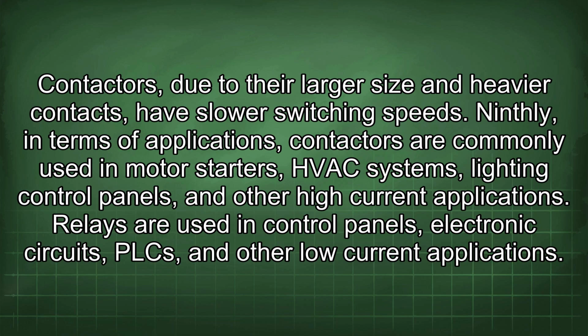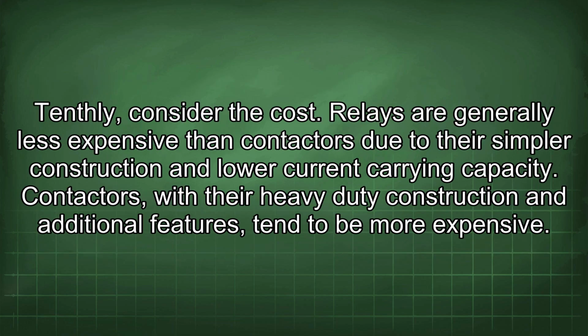Ninthly, in terms of applications, contactors are commonly used in motor starters, HVAC systems, lighting control panels, and other high current applications. Relays are used in control panels, electronic circuits, PLCs, and other low current applications. Tenthly, consider the cost. Relays are generally less expensive than contactors due to their simpler construction and lower current carrying capacity. Contactors, with their heavy-duty construction and additional features, tend to be more expensive.